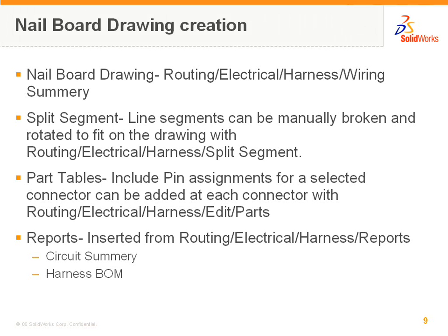When we have connectors, especially with multiple pins, we can insert part tables. These part tables include pinout assignments for each pin on that connector, and when doing this we can also display a wire fan out.